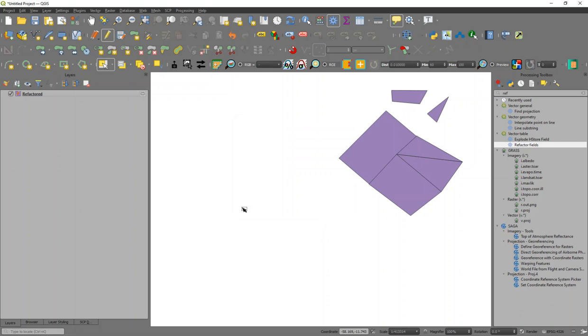For example, a keyboard shortcut that we use frequently is Control S for saving the project. Okay. Control Z, just like you use in Word or some other Microsoft product, you can use when you're doing various types of digitizing, and it will undo the last action. Sometimes if you hover over these tools, like the undo, it will tell you the quick key: undo, Control Z. New polygon, Control plus comma. Okay. So save layer edits, save project, Control S.